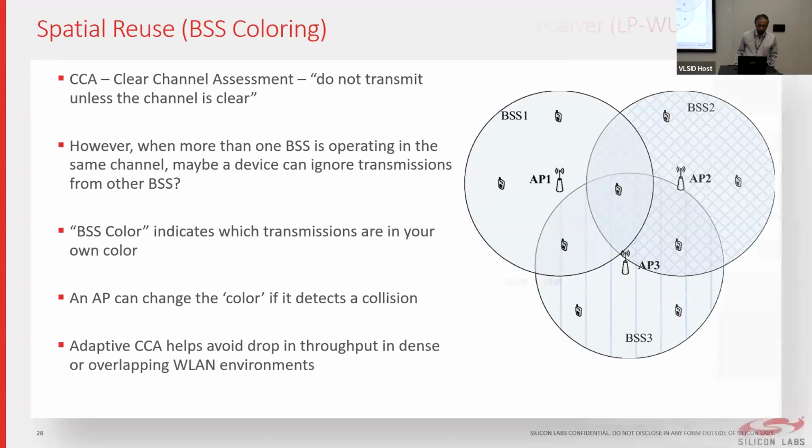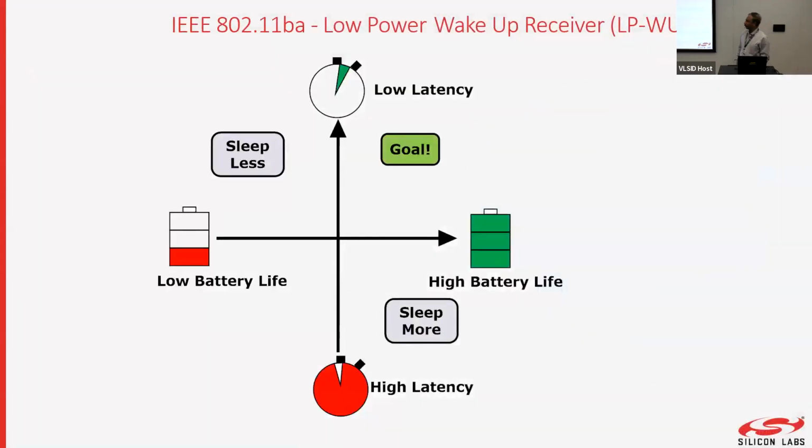Okay, so there's one more thing that system designers do, like I just now told you, which is deciding what is important for you, latency or battery life. If you can live with high latency, that means that you can wake up every 5 seconds. You can wake up every 5 hours. And if you are a controller which actually gives some information, if somebody decides to say that this road is now open, somebody sends the data, you're waking up after 5 seconds or after 50 seconds, and then saying that this road is open. That means there's a latency involved.